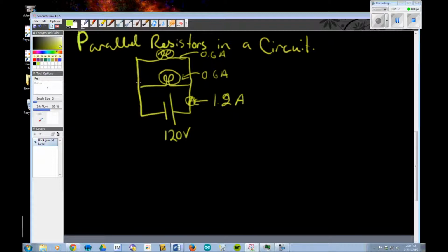So what we want to talk about is why is it and what's the mathematics of this? So the first thing that must be true is, if there's no bulb here, right? If this bulb weren't here, we'd have 0.6 amps traveling around this circuit. We measured that, okay? When we add a new bulb, we get another current traveling through this branch, and the overall current in the whole system doubles or goes up. So for current to go up, that must mean that resistance has gone down.